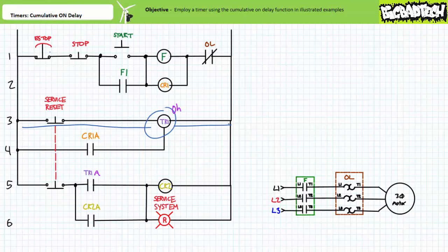In summary, the cumulative on-delay function for this circuit is acting like a record-keeping device and frees operator and maintenance personnel from this tedious responsibility. Applications of the cumulative on-delay function are numerous. However, they all generally behave in this fashion. Only after the controlling input has been energized, continuously or discontinuously, for the adjustable delay period, do the associated contacts change states. Alright, that is that for this lecture.